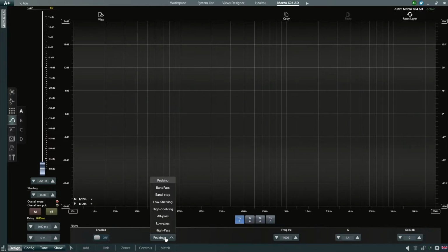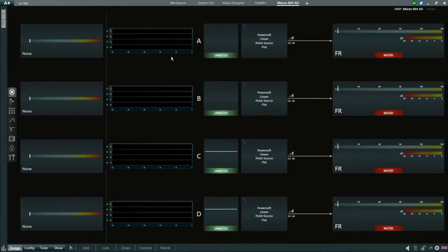Mezzo amplifiers, unlike the T, Canali, or X series, only support a user EQ delay time of 100 milliseconds, whereas the T, Canali, and X series support up to 2 seconds within their advanced EQ section. The Mezzo amplifier does not feature the speaker EQ section from within the T, Canali, and X series.